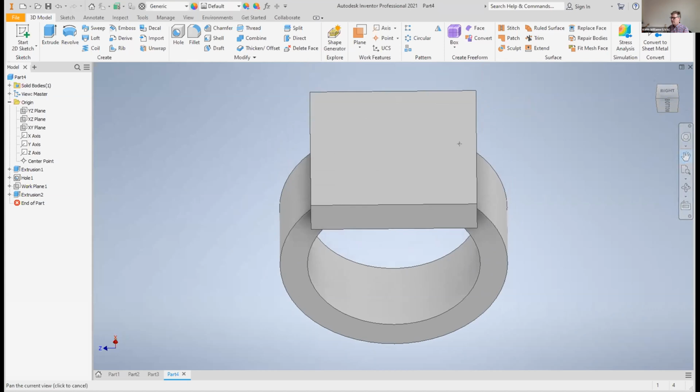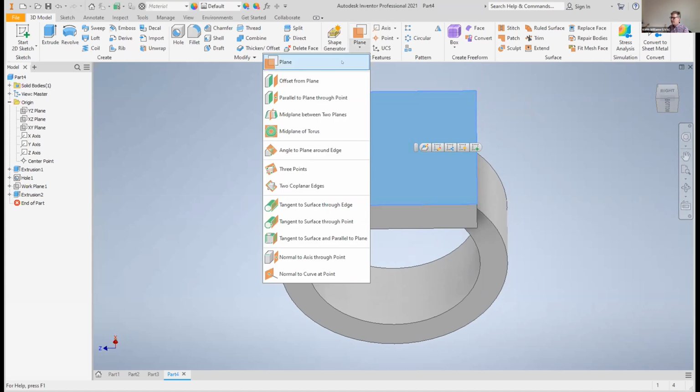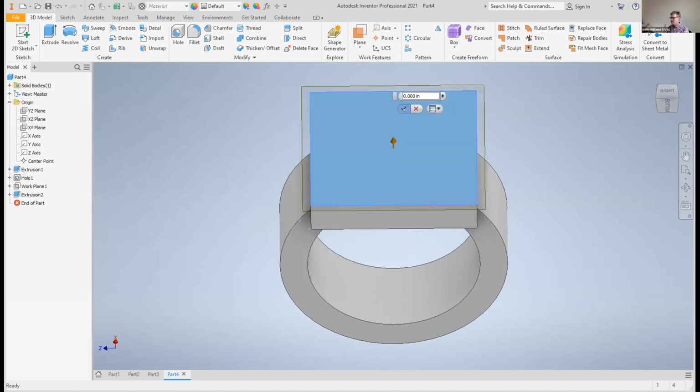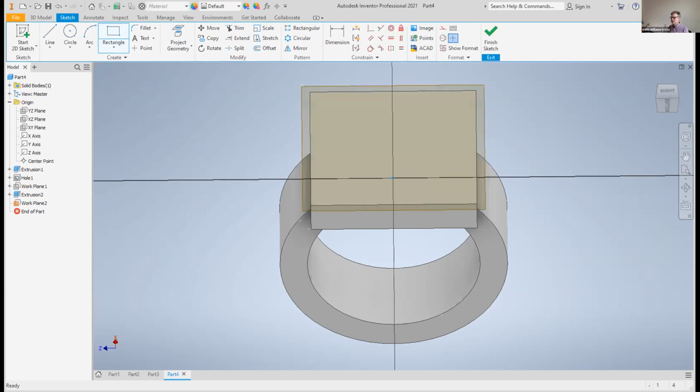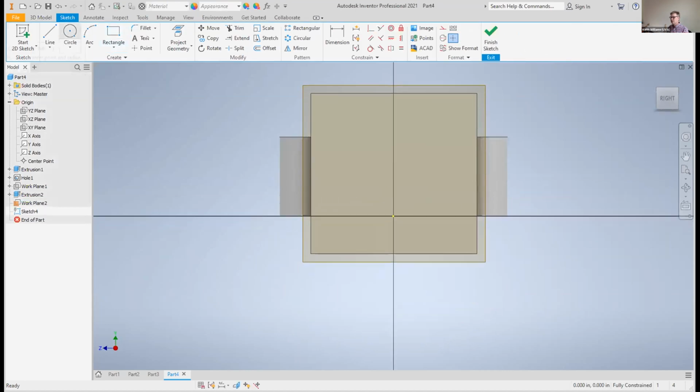So what are we going to put in the flat? Any ideas? Some text? I'll start with some text and then we'll get more elaborate. I'm really big on making offset planes, as you have probably gathered by now, even if the offset is 0. Because why? It gives me a named plane that when I click on it, I see work plane 2, and it just makes me feel good. It has a well-defined place to be. I feel like Bob Ross now. Everything in your painting wants a place to be. Don't you want a place to be? Don't you want your own plane?